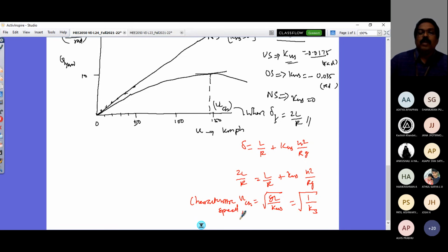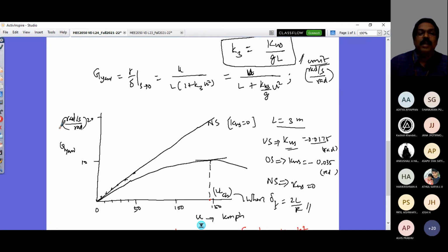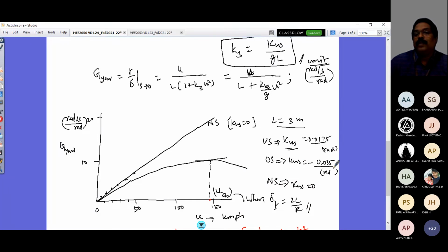Characteristic speed. So you can also say with respect to, that is this speed, that is this speed. Then if the vehicle parameters of the tire compliances in the front and rear in steady state motion are such that your understeer coefficient is negative, this is the case of the oversteered vehicle condition, and you would see that at that time the sign in the denominator is going to be minus.